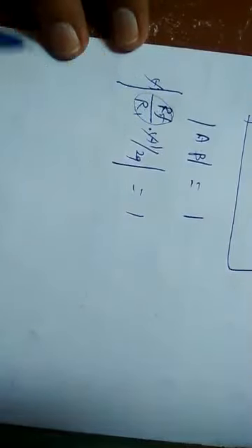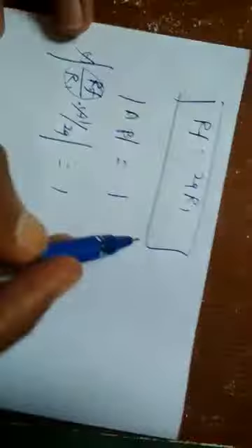Both will have minus, and the minus will cancel, so the absolute value. So here RF and R1 we have found an expression, that is RF equals 29 R1. If we choose RF equal to 29 R1, then 29 R1 by R1 into 1 by 29. So R1 cancels, 29 cancels, this will be 1.